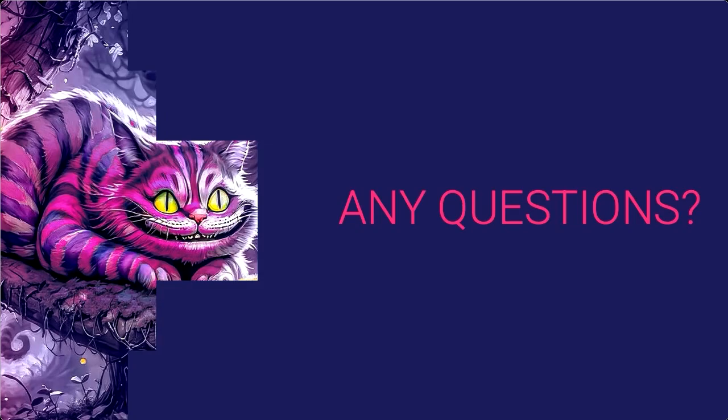So Harley, we're going to grab this last one here. How accurate are the filter design tools compared to real measured data? The Prodigy tools are extremely accurate. I wish I had included a slide, but if you want to see, please email support and I'll send you some measured data. The results from Prodigy, since that's an actual mimic design tool and it's doing full FEM quality filters, the performance virtually overlaps, within a fraction, like 0.1, 0.2 dB variation from what you're seeing in the simulation to what you're actually going to measure.